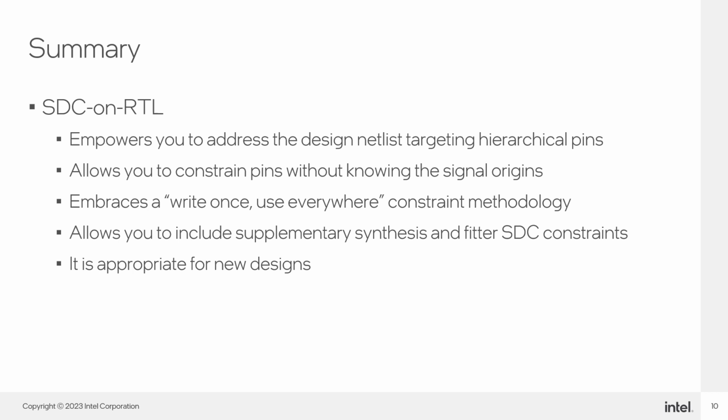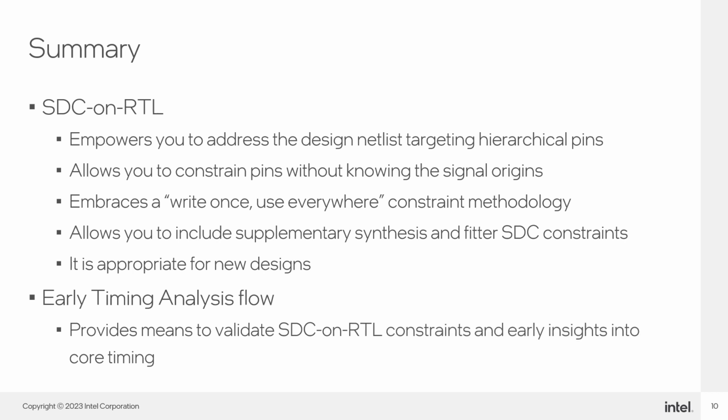Combined with tools like the RTL Analyzer and the Post-Synthesis Timing Analyzer, the early timing analysis flow provides an efficient means to validate constraint application within your design and gain early insights into core timing, all using your RTL design within the early stages of your design cycle.